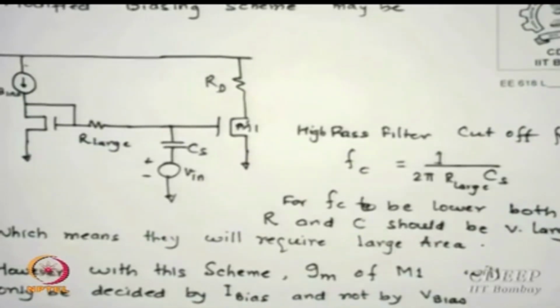Okay, and that's exactly what the differential amplifier does. Why was this a precursor: to show you why differential amplifiers became so important, apart from many other advantages of differential. One of the reasons was that the biasing became very trivial in the case of a differential amplifier, because even if it is not constant, it takes care of it. And that is some fun part in that. The differential amplifier gains are normally very stable gains, and that is why we prefer differential amplifiers.